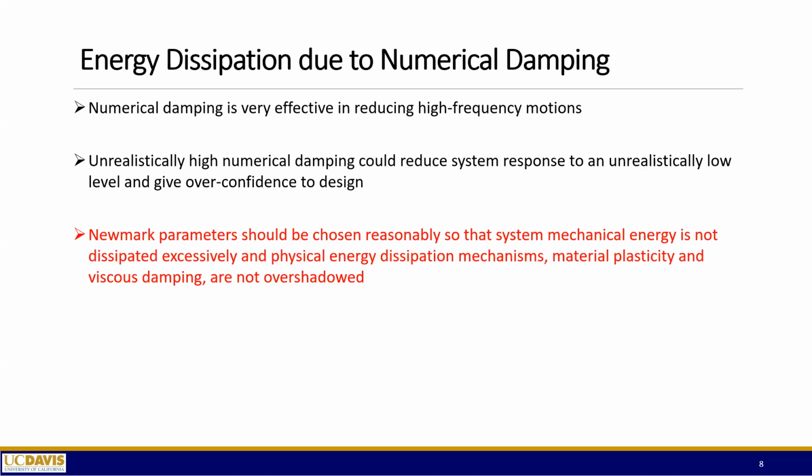And so if, for example, you're looking at the peak ground motion or peak displacement, you might actually get something that's okay. You maybe get a false sense that you can use one energy dissipation term to cover the other. However, if you look closely at the detailed response of the system, you will see that the different energy dissipation mechanisms actually give you very different system responses. And later we will use a rather simple example to show you this point.